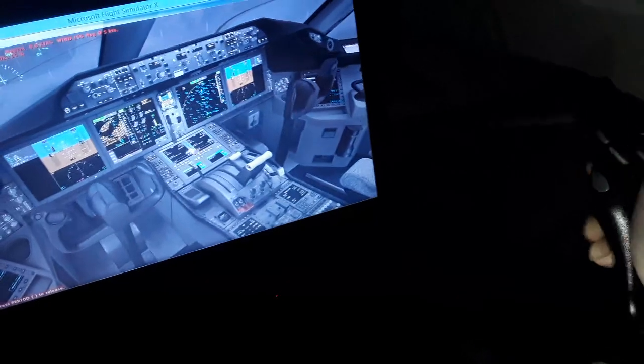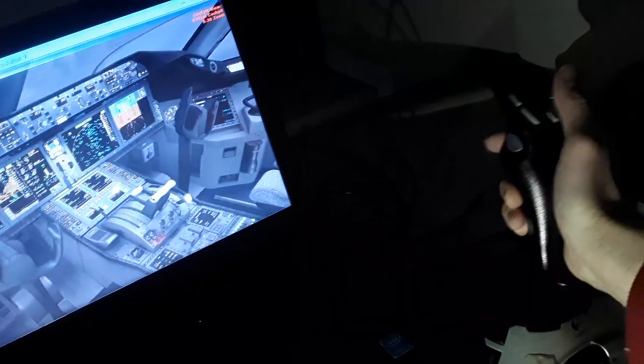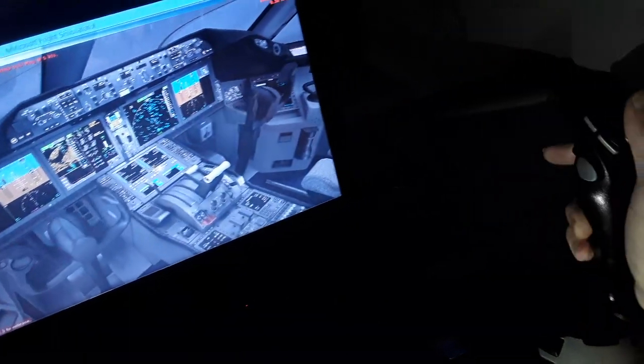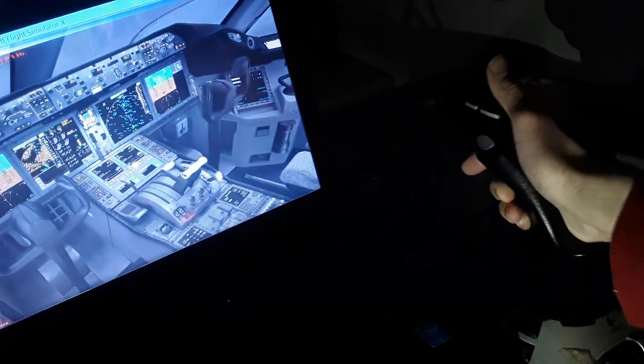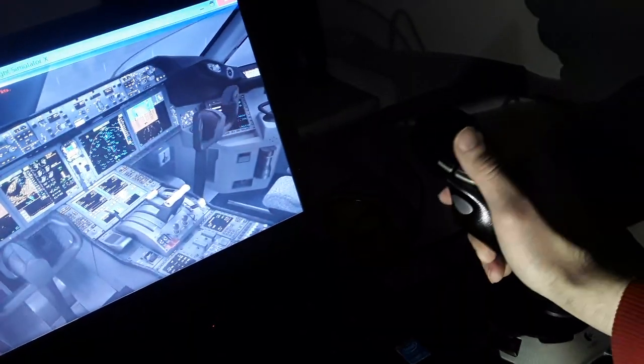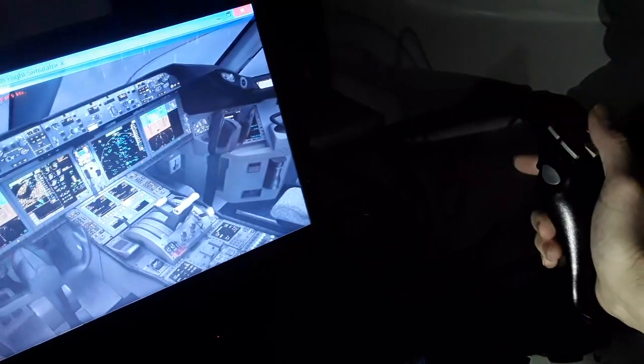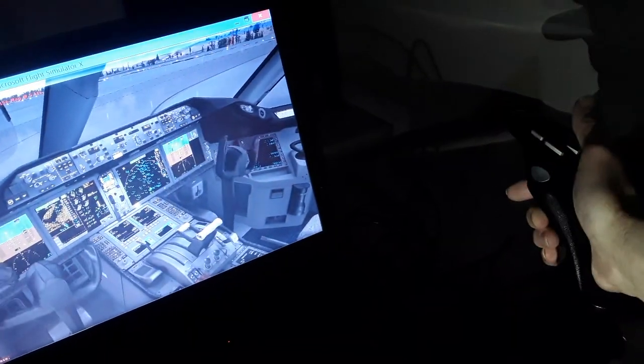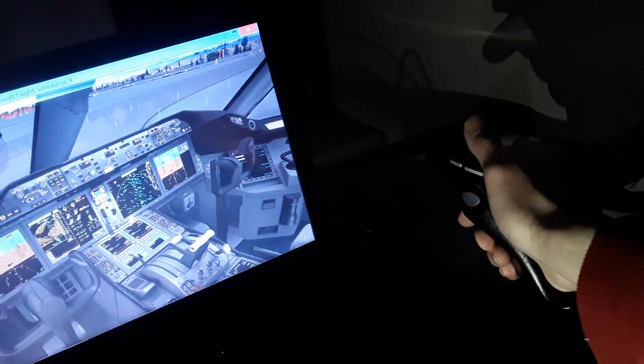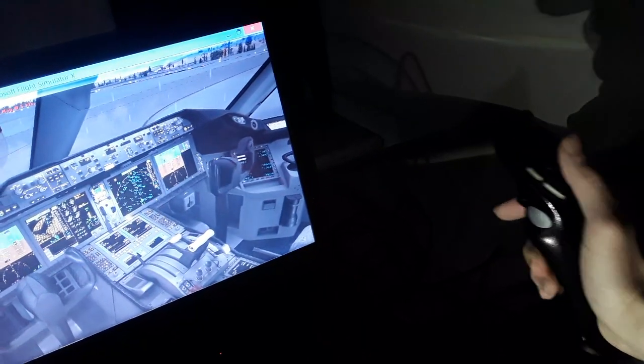You can use all flight controls together, full movement, just like in the Airbus, and also in the Boeing you have full flight control, coordinated flight. Also you can see in the Boeing the flight controls move together, they're interconnected, both the captain and the first officer. Unless you want to override one side, you use more force, or if you have a failure, you override again using force to control one side more than the other.